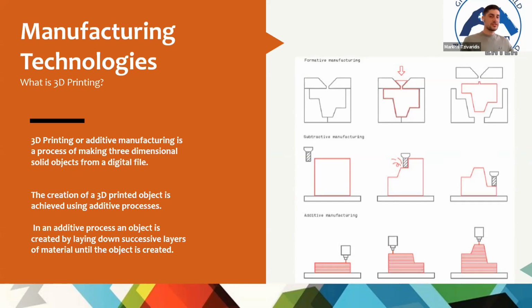This process, of course, is easy. You simply add liquid material inside the mold and it becomes solid. The way you can produce the same object over and over again is just to simply add liquid and subtract it again. So what is the disadvantage of this process? Basically, if you want to redesign the model, the mold should be recreated so that the final object will be recreated. So this takes a lot of time since the mold is not easy to create.